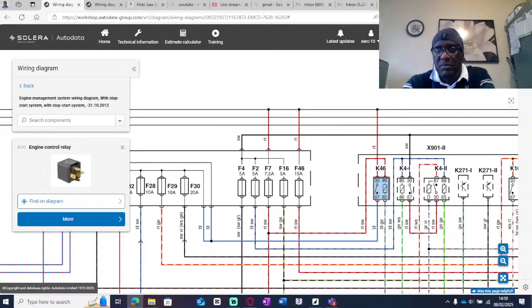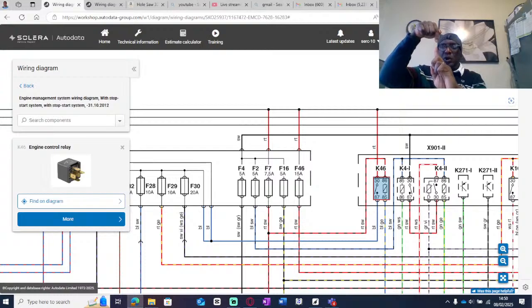There are differences between a GDI and a port injection system, in the sense that besides fuel being injected directly, the piston shape is different, because they've got this piston that has got recesses on both sides. So the air comes in, tumbles, hits this area, and goes right to the top. The fuel comes in one side, also hits this piston, and goes to the top. So this area here, where the plug is sitting on top, has a rich mixture, but the whole cylinder has a lean mixture. That lean mixture then insulates the cylinder from losing heat.